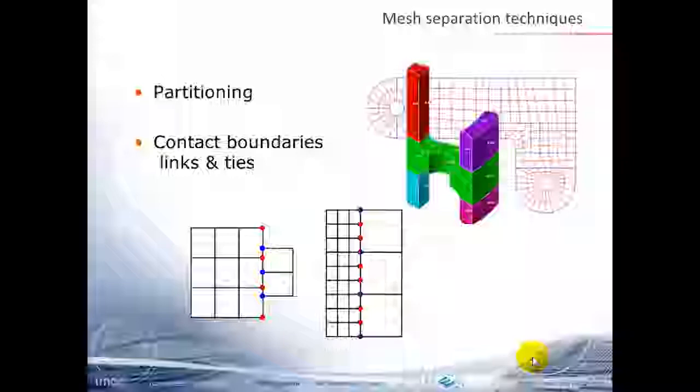Another thing you have to be aware of is that if this is a thermal model, you can maybe nicely have convergence on the temperature, but are you sure that the energy exchange, the heat exchange between both, is respected by your contact boundaries? So you have to treat those things with care. But there are, of course, a lot of types of boundary contacts.